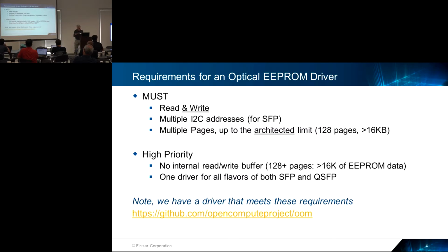So moving to the driver, what I need in that driver to do what I just described, I have to be able to read and write. Surveying the drivers I have seen, I haven't seen anywhere near all of them, but we're just talking about SFP, QSFP, EEPROM drivers. Many of them don't write. And if they don't write, I can't control the device. I can only read from it.